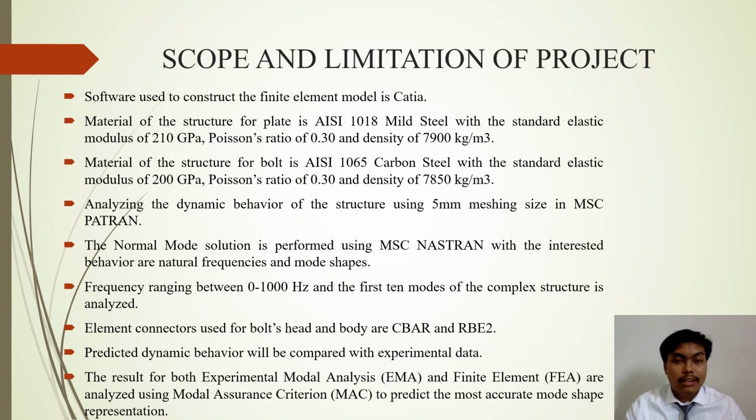C-bar is used in the study because, number 1, it can define torsional, bending, and shear stiffness, and number 2, because it has the same cross-sectional area and material properties on the 4 bolts together. Thus, the predicted dynamic behavior will be compared with experimental data.